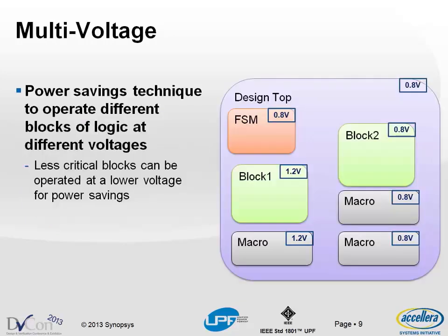And then we move on to multi-voltage. This is basically saying, hey, I've got a design, and instead of you, the designer, trying to manage each of these by hand, which I believe some or most of you have done in previous designs, you can do it in a more automated fashion by saying, I've got a design, and I've got discrete voltages for different portions of the design. And the tools themselves will automate and take care of making sure that all of these are operating at these voltages and have the proper signal levels passed through. This way you're not trying to do your own homegrown hodgepodge. This enables you to have more automation to get this multi-voltage design.